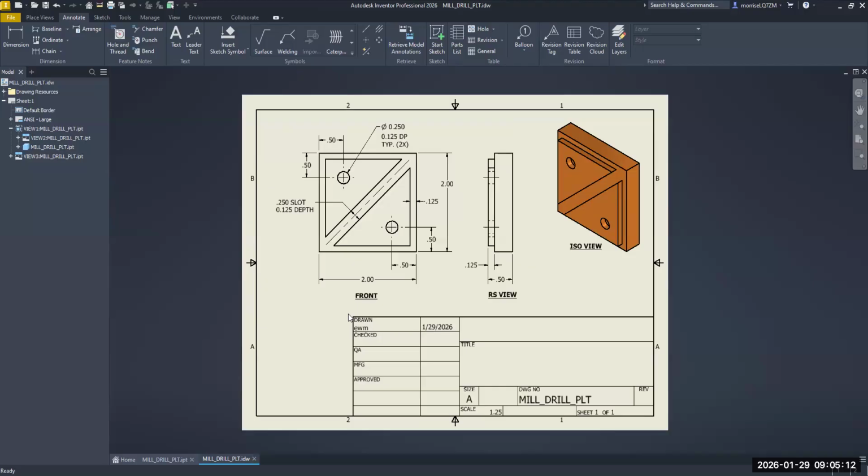Okay, so here you go. We got to do the border. Everybody with me? Come over here. Look, come over to your browser. Here you go. Because a lot of people never fill this out correctly. Mr. Morris is pretty much a stickler for this. Mr. Middleton may not have been. I don't know. Come over to the browser, do a right click on this, iProperties.